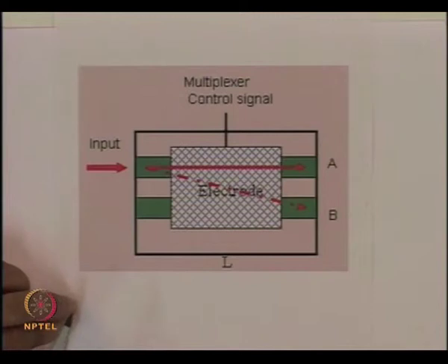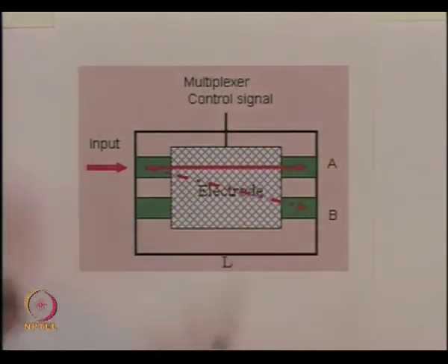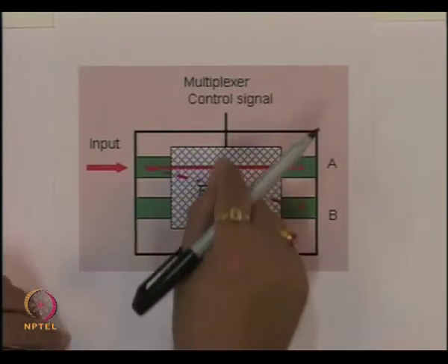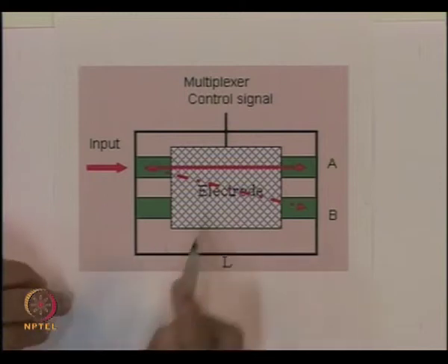We can develop further based on this principle now. Again, we take the same configuration here, and now you have an electrode signal which need not be data, but a certain voltage which you can change between two levels, and the level change essentially changes the coupling length.